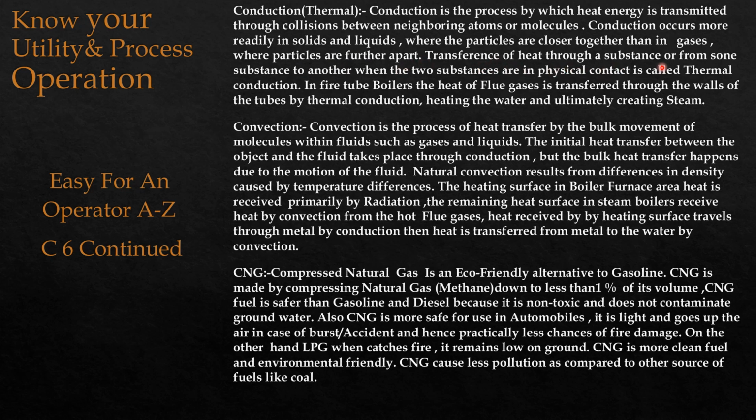Transference of heat through a substance, or from one substance to another when the two substances are in physical contact, is called thermal conduction. In fire tube boilers, the heat of flue gases is transferred through the wall of the tubes by thermal conduction, heating the water and ultimately creating steam.